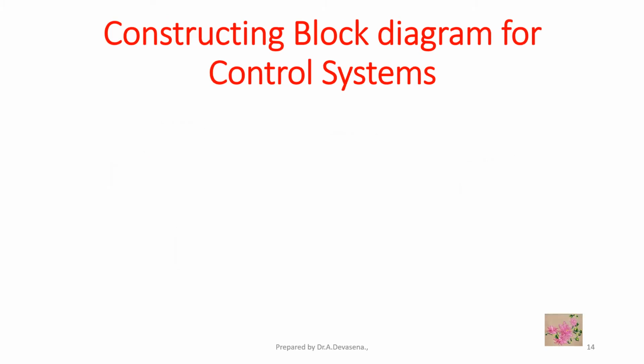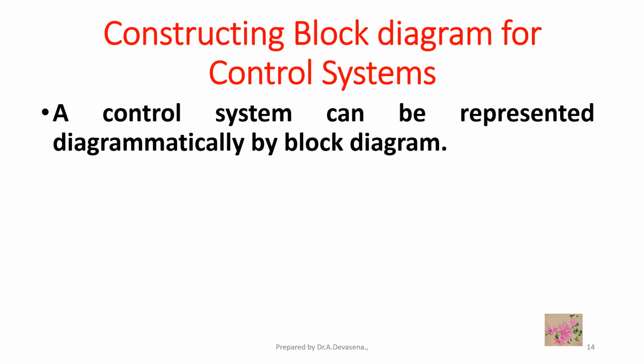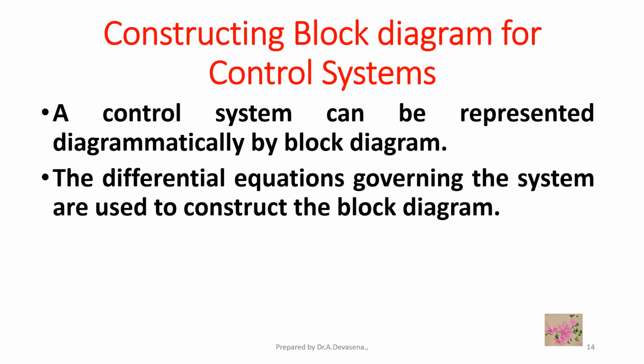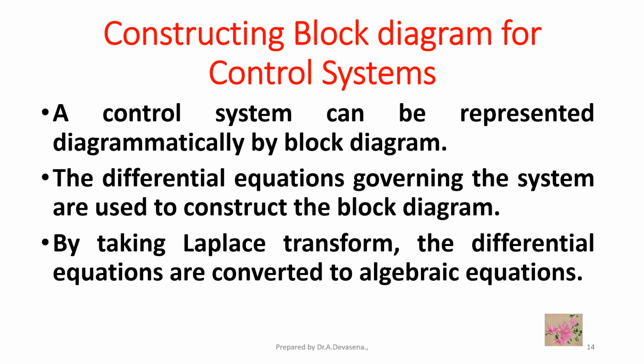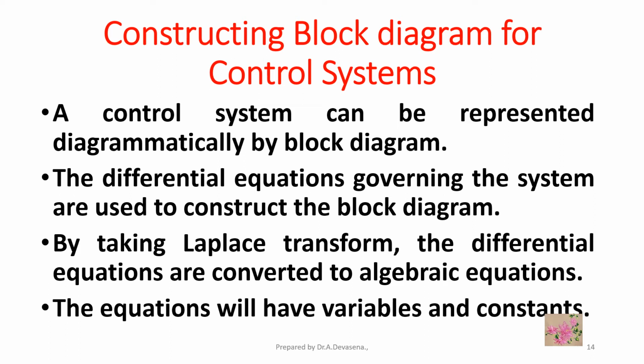Constructing block diagram for control systems. A control system can be represented diagrammatically by a block diagram. The differential equations governing the system are used to construct the block diagram. By taking Laplace transform, the differential equations are converted to algebraic equations. The equations will have variables and constants.